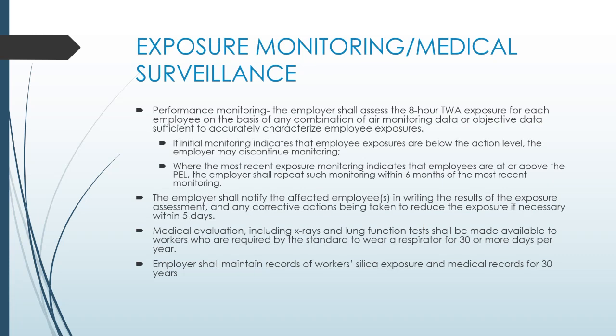So let's talk about exposure monitoring and medical surveillance. This is when we know that there is crystalline silica and the potential for exposure. We're going to make sure that you're not being exposed beyond the permissible limits and hopefully not being exposed at all. But as you're doing your work in this atmosphere, we're going to give you initial monitoring.